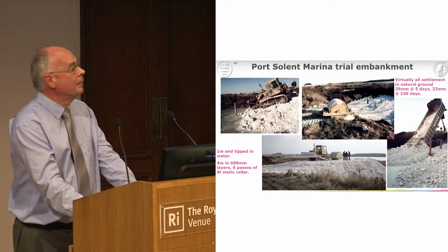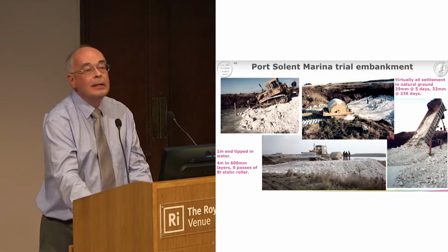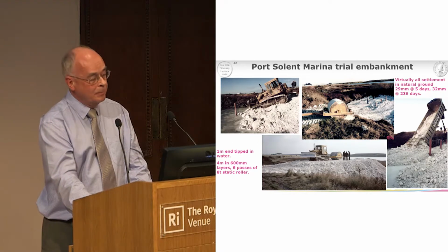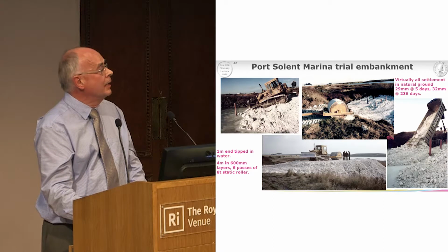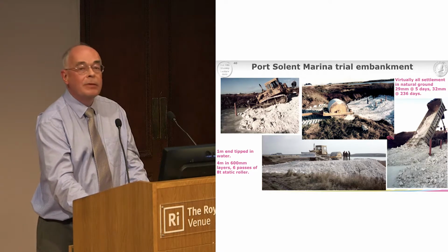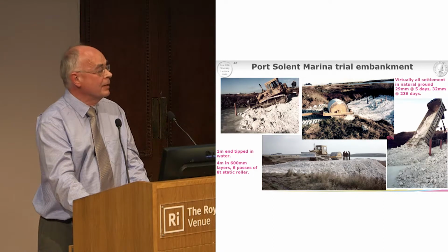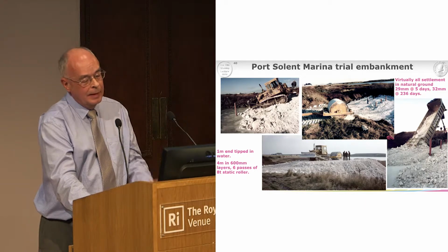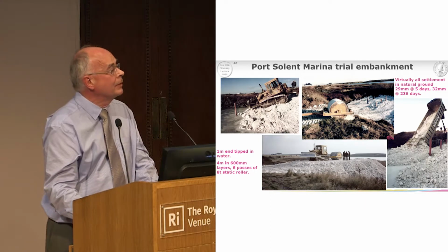And here's the work in progress. The first metre was actually just dozed into water, and then the next 4 metres were placed in 600 mil lifts with 6 passes of an 8-ton roller. And that's the finished project at the bottom.